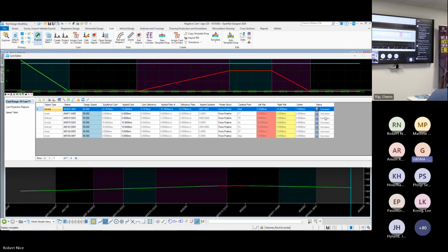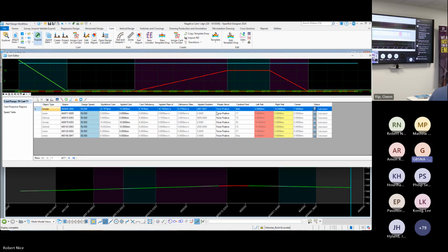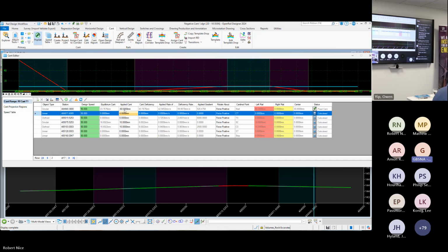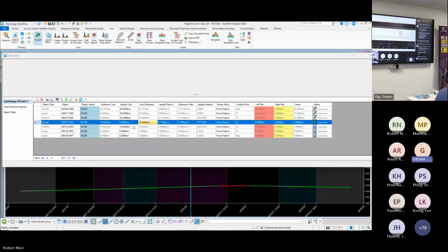I'm going to move up because it's in the way of the dialog box there. So pretty similar to what you've already got. It's a table. That's it. The only thing different really is rotate about. You've got false positive. And in this thing, we want it to be -60. And Phil can, while I'm typing in, explain why we're doing this. So we're forcing the cant to be 60 mil negatively applied, and there's again some really good information found just on an AMP file. But by applying that -60, it knows to put the cant onto the opposite rail.